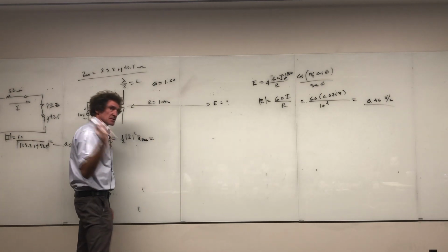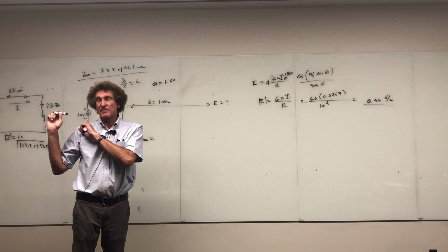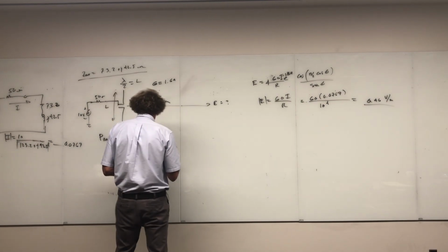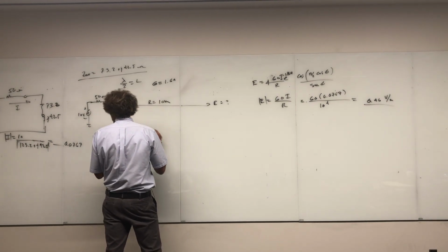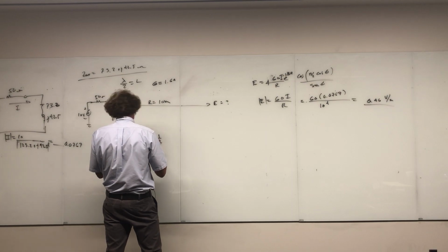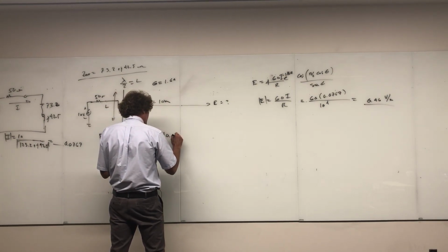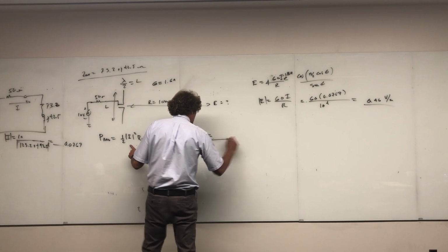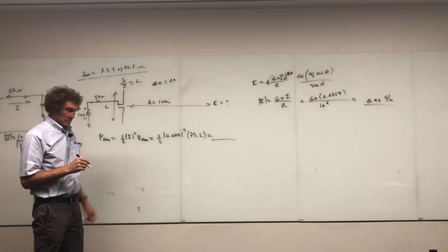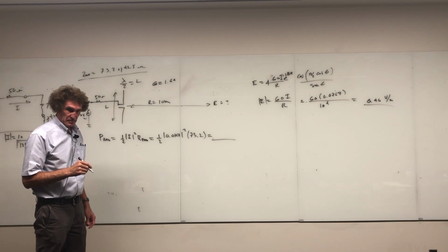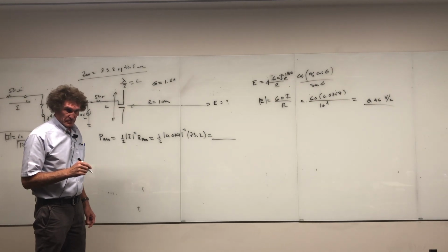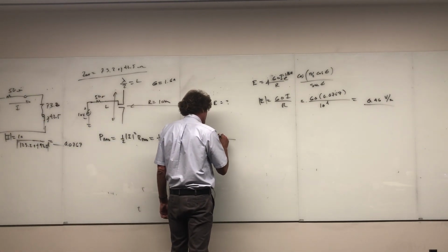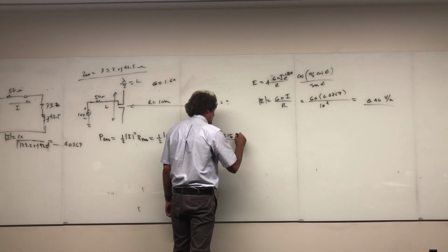What is the radiation resistance of a half-wave dipole? 73.2 ohms. All right, that accounts for all the radiated power. Agreed? So it's going to be 1/2 times the magnitude of the current, which is 0.0767, squaring it, times 73.2. So tell me the total radiated power here. I got 0.215. Anybody else confirm that? Yep. And 215 watts, right?